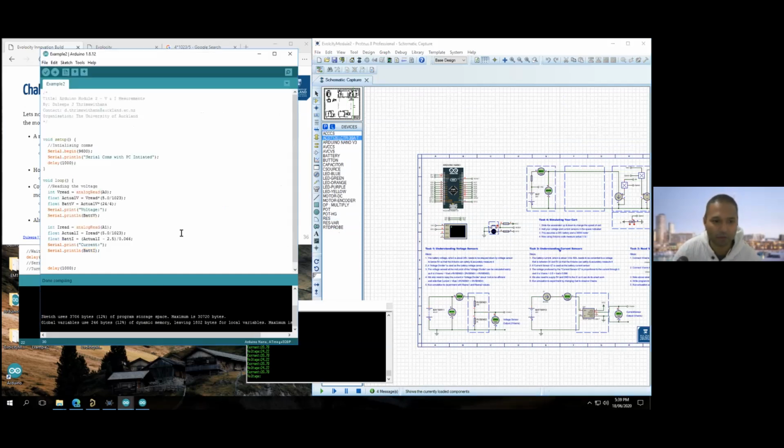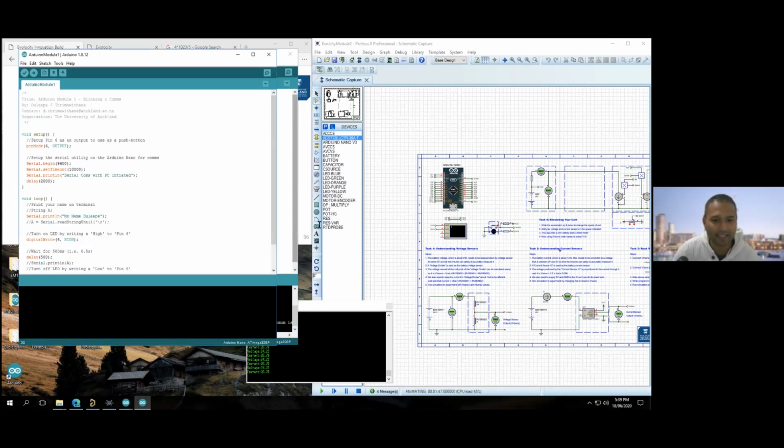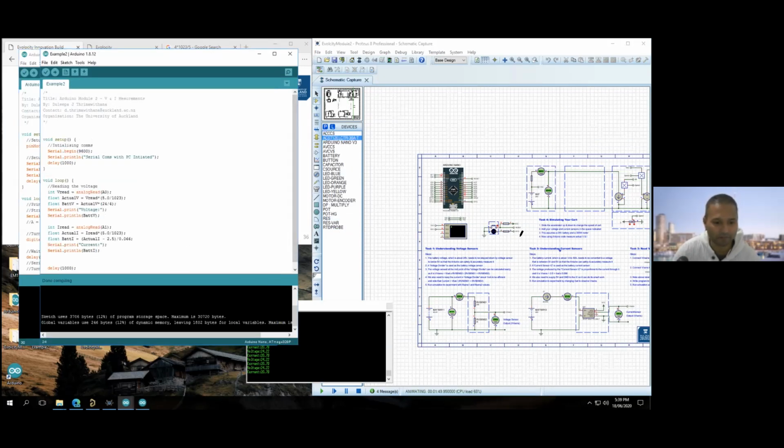The software you have written should work, but improve it so that it can read power too. So how do you figure out power? Power in a circuit is equal to the voltage times the current. Do we know the voltage? You already worked out the voltage. You already worked out the current. So we just have to put another statement saying float power equals battery current times battery voltage. Then you can print the power, voltage, and current coming from the battery.